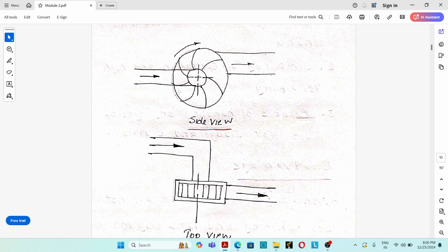When the impeller is rotating, a vacuum pressure will be created in this portion. Due to this vacuum pressure, the atmospheric pressure acting over the fluid surface will pull the fluid into the eye, due to this pressure gradient. When the rotation speed of the impeller is low, low vacuum pressure is created. When the rotational speed of the impeller is high, high vacuum pressure is created.